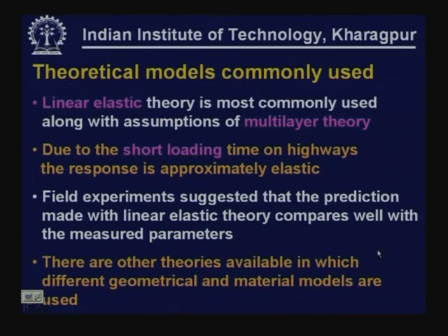The commonly used theoretical models for analysis of flexible pavements are: linear elastic theory is the most commonly used theory, and the geometric model that is used is layered theory. So, linear elastic layered theory is the most commonly used model for analysis of flexible pavements. Layered assumption we understand because pavement is a layered system, but we have to be justifying the assumption of linear behavior of pavements.